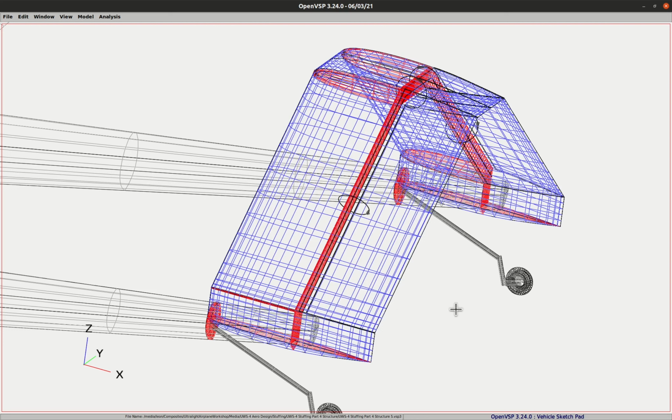And once again, hinge locations, there's going to be a hinge for the control surfaces up here and down here. And also this is going to be a trim surface back here, so we're going to have a couple of hinges in here. And then right down here at the bottom, in order to handle this shape, this will probably be just a fiberglass covering that we put right down in here.